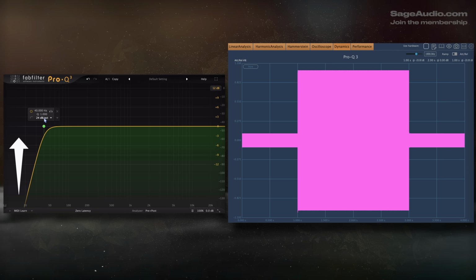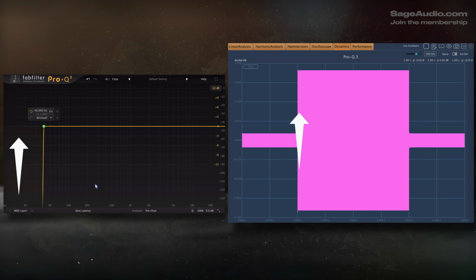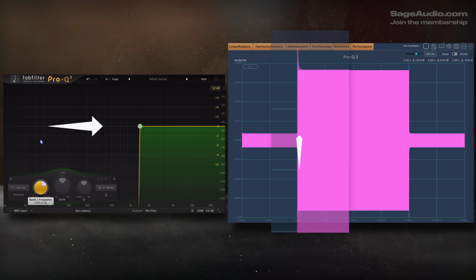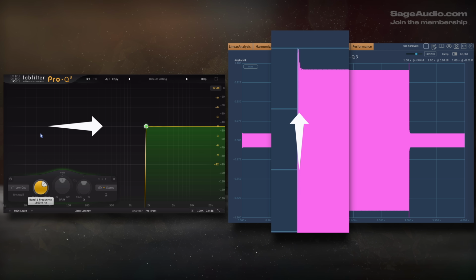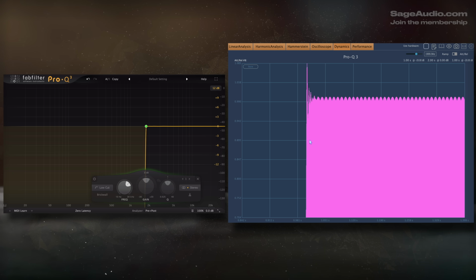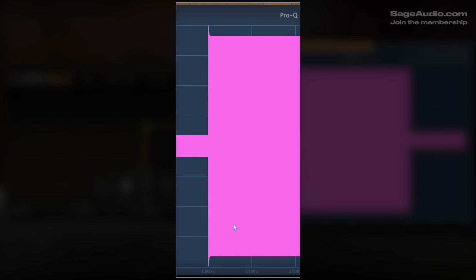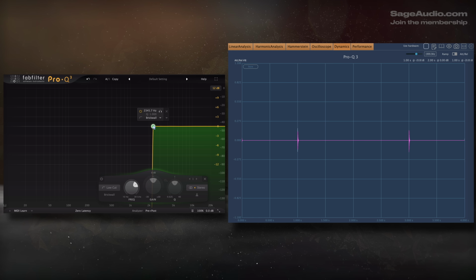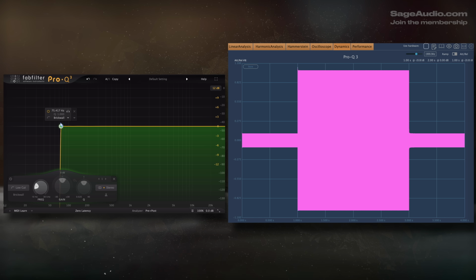If we increase the filter's slope, the alteration becomes more aggressive. As I increase the cutoff frequency, closer and closer to the frequency of the sine wave, or 2 kHz, the distortion and subsequent alteration to the dynamics becomes more significant, with the most significant change occurring around 1.8 kHz. Additionally, notice that it takes roughly 20 milliseconds before the amplitude adjusts back to the intended value, definitely long enough to be noticeable.